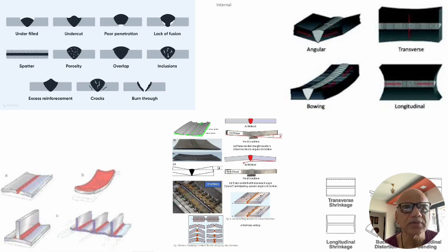The second defect type is where we can see it with the naked eye. Like the first one, underfilled: we can see that welding has not been done fully into the groove if that is required to be filled up. The obvious remedy is that we need to add more runs and ensure that the weld groove or the fillet or the overlay or buttering or the other applications of welding which are used are completely done to what is required as per the standard code or the design.